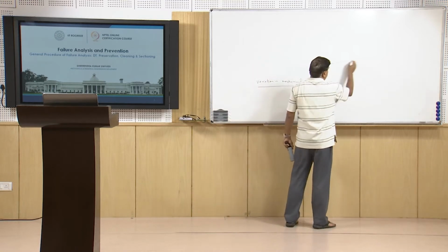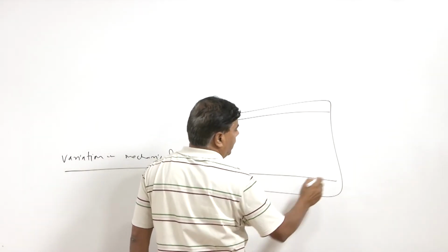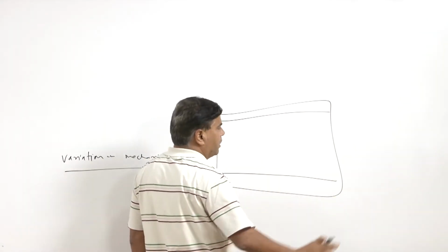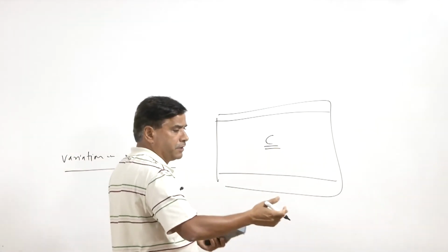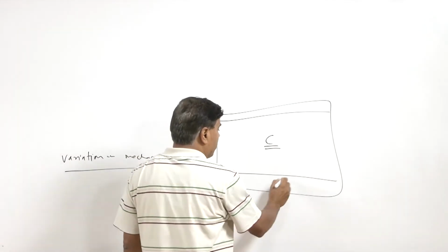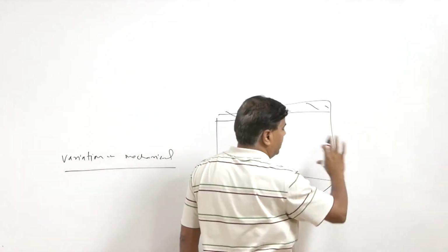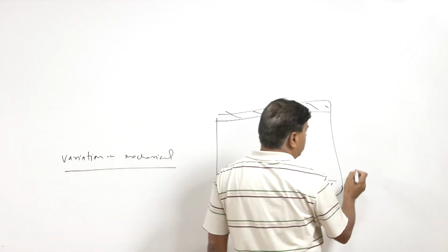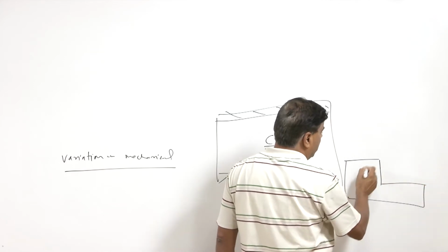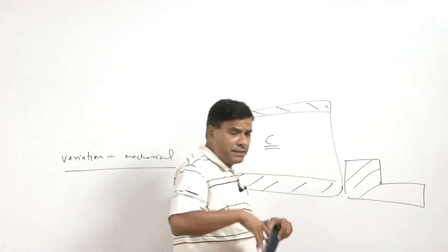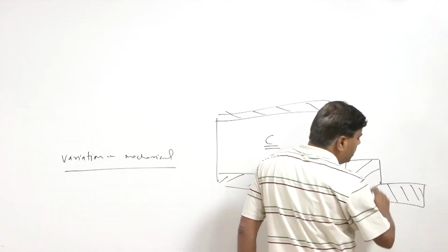Like if the component is really very large in size, the surfaces will be experiencing more stresses, more deformation, more thermal load, and the core will be getting a different kind of thermal and mechanical history. So, the surface layers will be offering a different kind of behavior as compared to that of the core. Similarly, if the section sizes are different, like here one size is this, another size is this, the one which is bulky will be experiencing a different cooling rate as compared to the other one, and that is why the cooling conditions may vary.